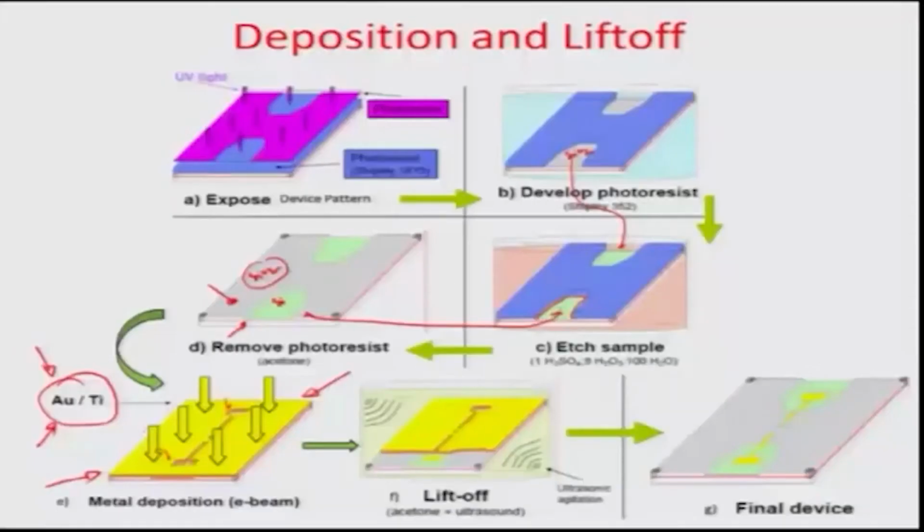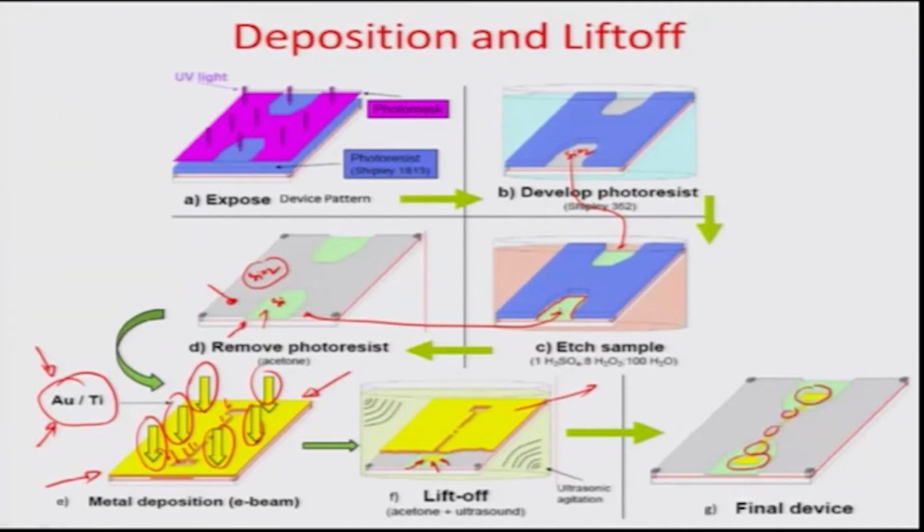So you are depositing this gold titanium layer on the top, and because of which there are certain selected regions, which are the cavities as shown here, which have the deposits of gold titanium, and then you remove this layer away, so that the gold and titanium has an adhering capability to this green Si substrate later on. So they adhere the gold and titanium in this region, and this is how you do printed electronics.